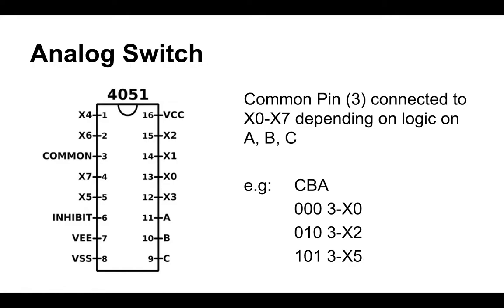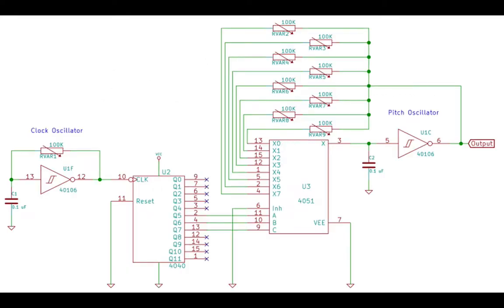So this circuit is pretty fun. It's kind of daunting. But if we look at this, right, this is our 4106, this first part. This is our oscillator. And this is our 4040. What I did was I took 3 of the lowest frequencies, 3 of kind of the low frequency oscillators, and I put those into A, B, and C. Okay?